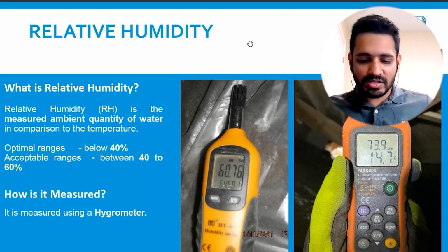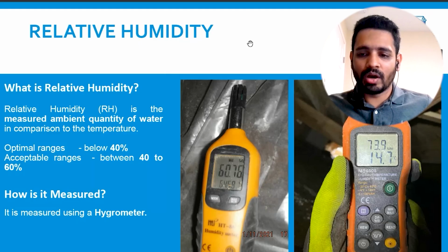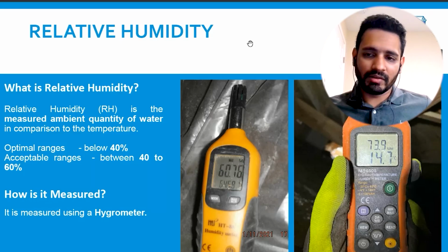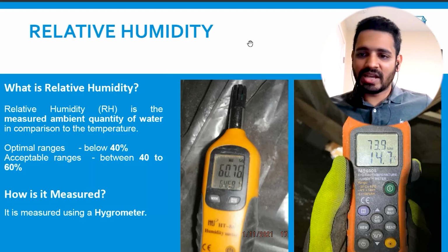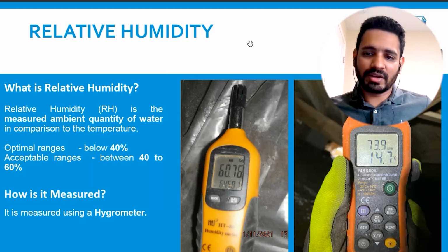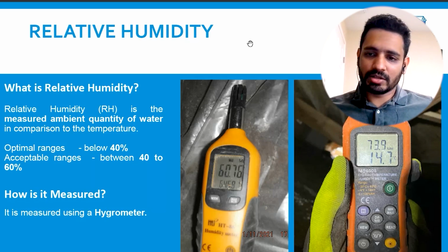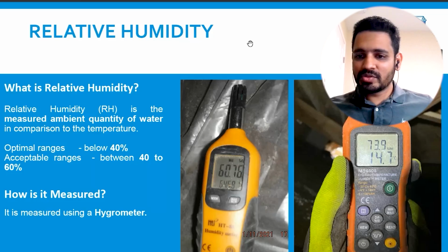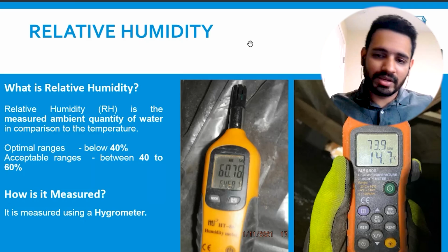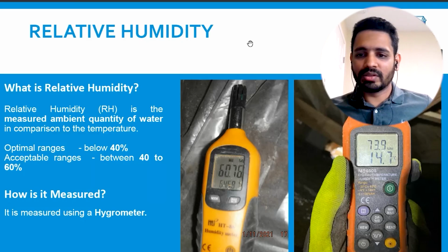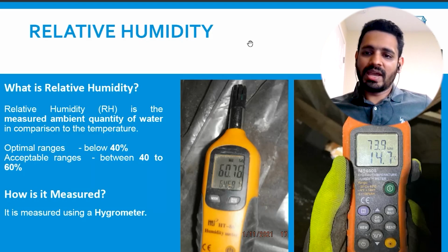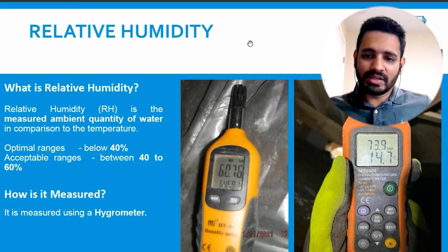And sometimes there is a difference between a moisture problem and a water problem. A water problem is typically associated with a drainage issue. A moisture problem is associated with water vapor in the air of the crawl space that doesn't cause standing water per se, but starts to affect the other areas inside a confined space. So we take a hygrometer, we put it in multiple spots inside a crawl space or a basement, let it stabilize. And sometimes you would have interior foundations which kind of close off the portion of the crawl space. So we make it a habit to put it in different spots so we can find out what the maximum is, what the crawl space average is, and if there are any further recommendations to lower that relative humidity inside the crawl space.